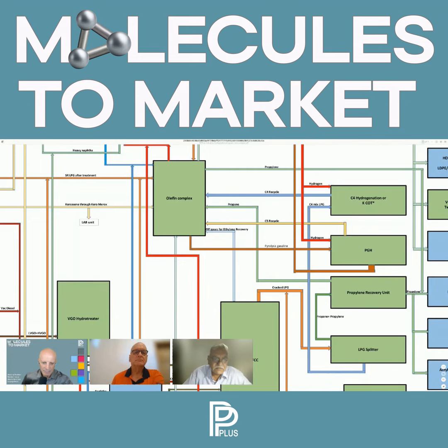What happens is the consultant begins to make the equipment layout subsequent to receipt of the basic engineering package from the licensor. Once you do the layout, you have to re-perform the hydraulics. In the process, a lot of line sizes get changed, whatever the licensors have offered. Now, this is tragic. If you keep doing that, then we are losing precious time.